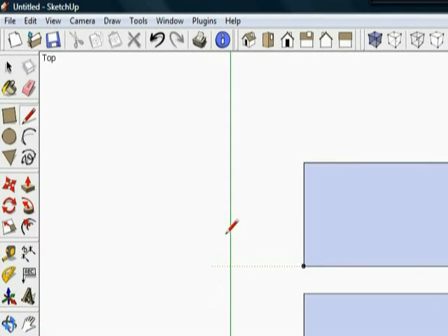Now, while I have this drawing tool, there's a neat thing that SketchUp allows here. Sometimes I want to find the exact center of a line segment. If I just put my pencil tool on there, you'll see that I've got a little red dot, but as I slowly trace down, now that dot is snapped in and turned this bluish greenish color, and that tells me I'm at the midpoint of a line. That's something you can use to your advantage in drawing and assembling your three-dimensional models.